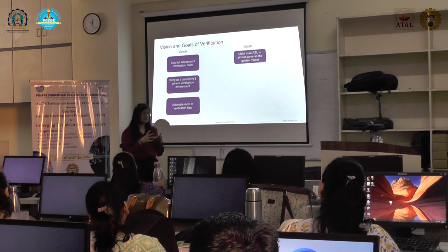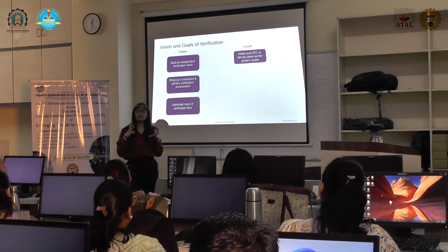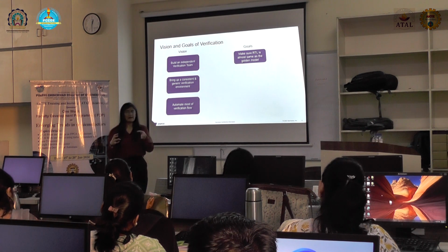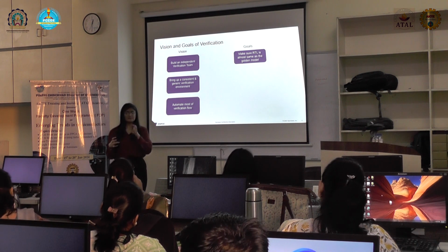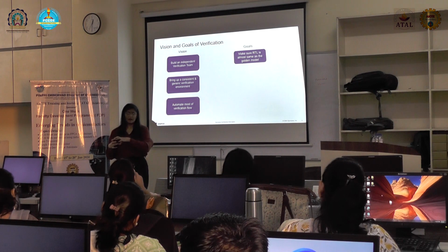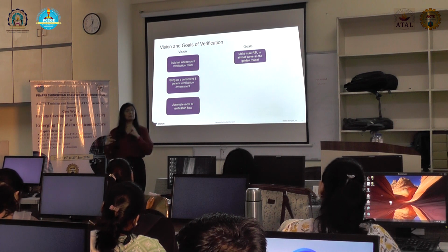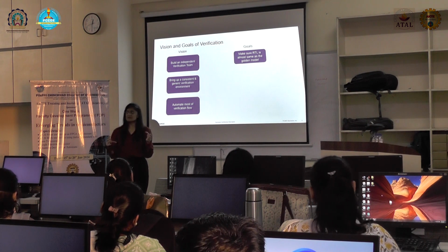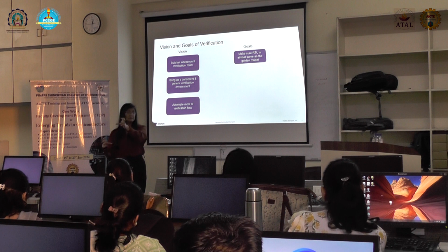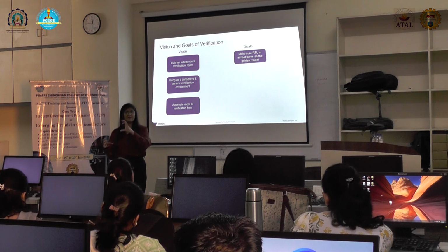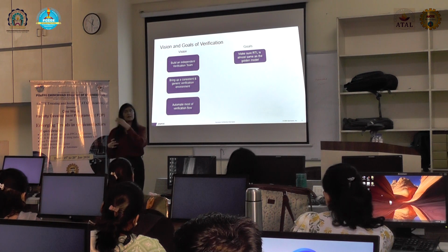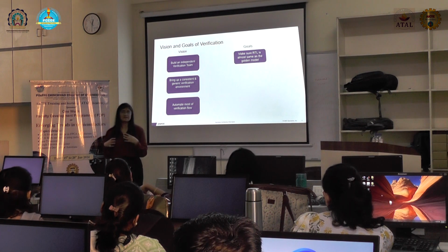So we have to focus on RTL and the golden reference model. What is the golden reference model? The golden reference model is mimicking the RTL. It's not exact RTL. It's mimicking RTL according to the specification so that we can compare it with actual behavior. So the golden reference model is specification oriented. It's not implementation oriented. Implementation oriented outputs will be created by simulation runs, and we will compare them with the golden reference that we have.